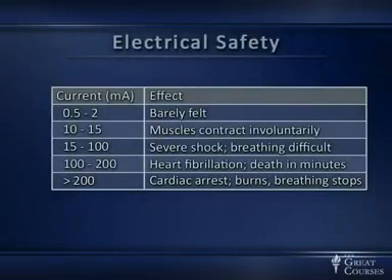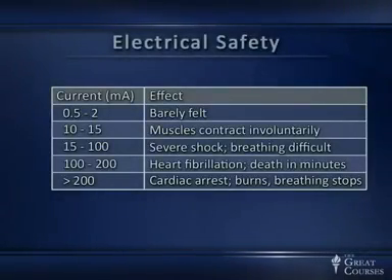The currents it takes aren't that big. Currents through your heart of microamperes will upset the electrical system. Your heart is an electrical system, as we've seen, that paces your heart. So they can be pretty small. But usually you don't get currents very big inside your body unless you've introduced some kind of electrodes into it. So let's look at what's going on here. Current is what's really dangerous to us, but it takes voltage to drive that current.